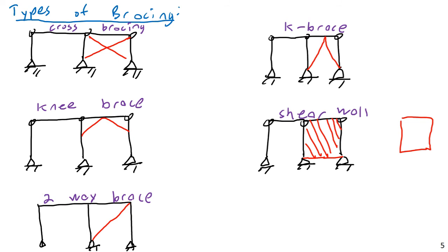So in cases like that, it also illustrates that I've labeled these as very much an either-or option, but in reality, in real structures and real buildings, it's not either or. You have many different options, and in fact, in a big steel building like that, you might have all of the above. You might have shear walls, you might have braces, you might have some moment connections in there. It really depends on the architecture, essentially. So in some areas of the building, if a particular frame is going to be embedded in a wall anyway, go ahead and put a brace there. Why not? Save on the complicated connection.